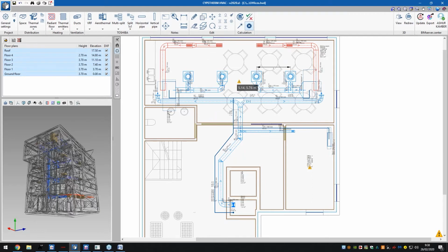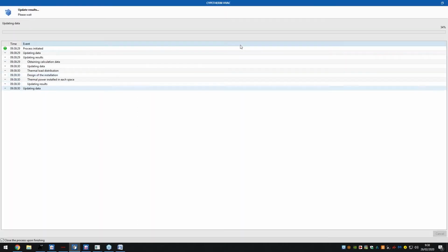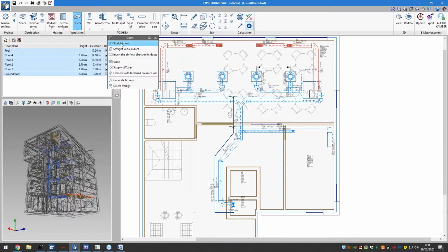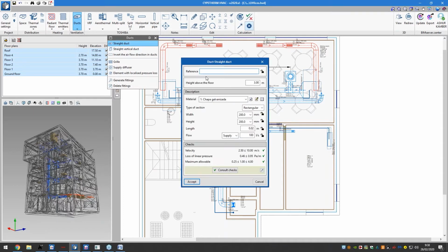And you can see as well, upon those checks being done, I'm able to go into particular results and update them as well. Now, upon updating those results, we get those checks, and then I can intelligently design my ventilation, etc., pipes, and so the program actually aids me in doing that. Let's have a look at maybe defining an exhaust system. So we can come over here. We can insert a straight duct.